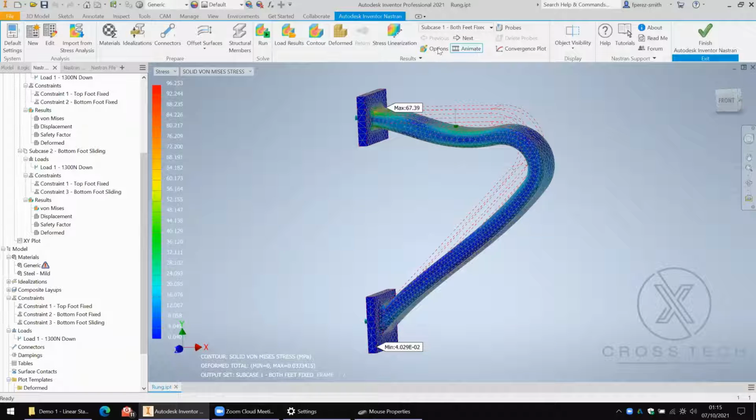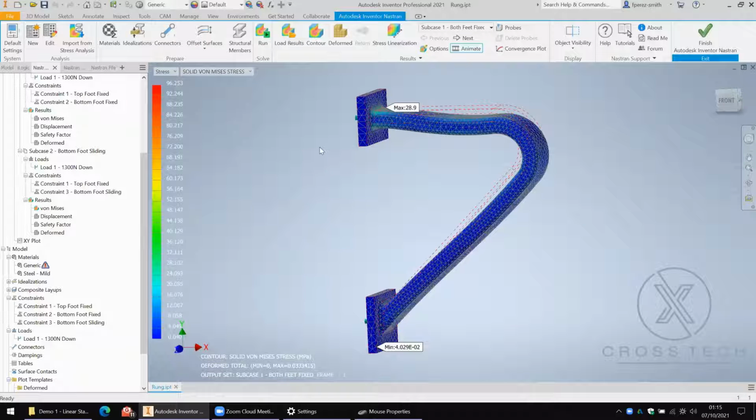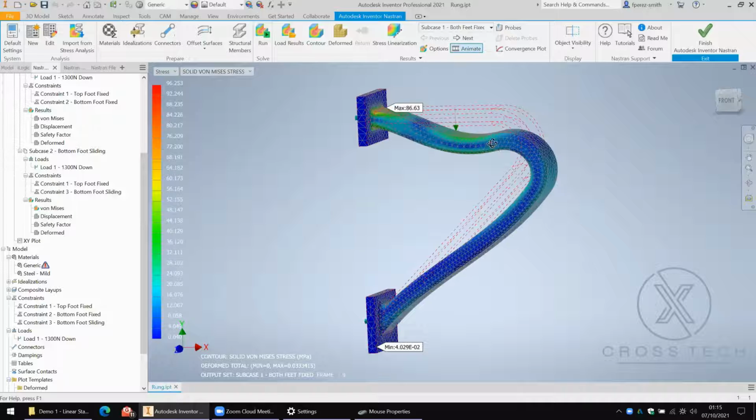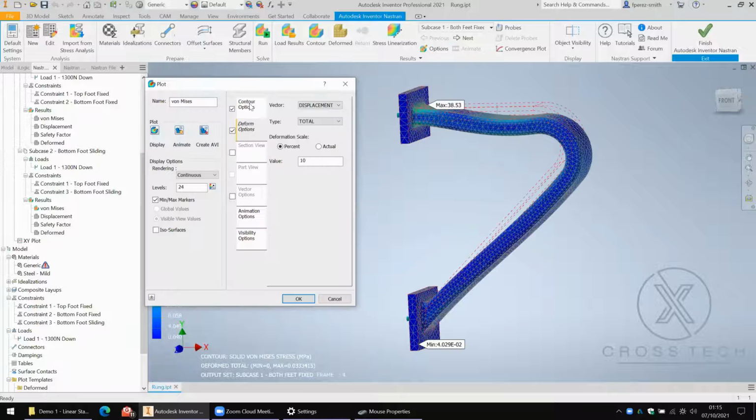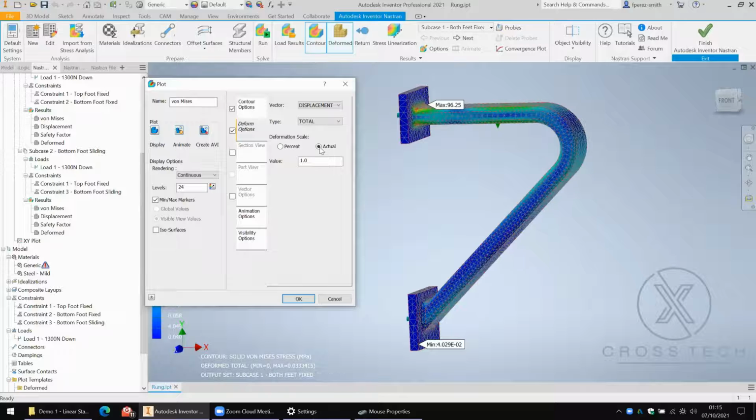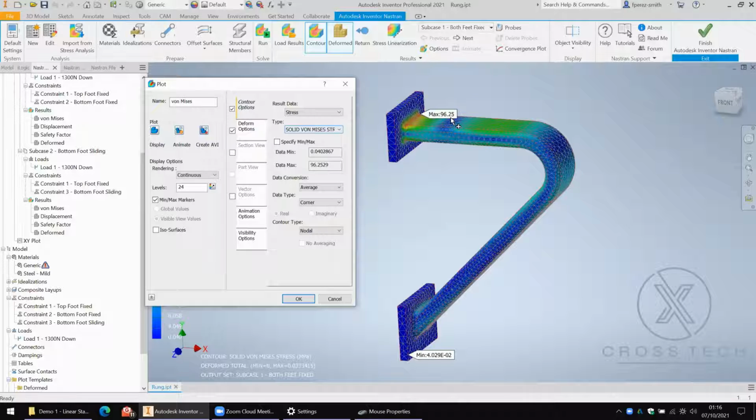What we're going to do is just quickly show you the options. And here we can see the deformation. So we can actually change it to the true deformation, which, while more accurate, is probably less interesting to watch. That's the true deformation. You can barely see anything. So we have many, many metrics that we can see. By default, we're looking at the von Mises stress. The yield strength of this material is 207 megapascals. From this calculation, we can see that the von Mises stress is 96 megapascals, which is less than 207. So we're not expecting any plastic deformation, with a caveat to be continued.